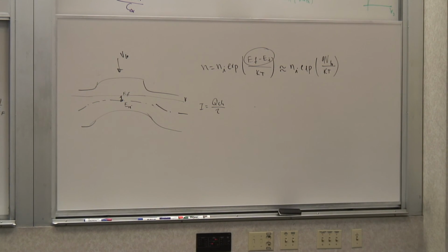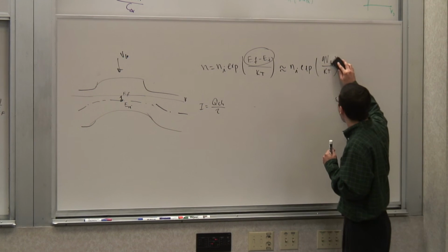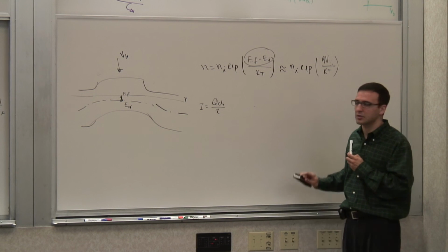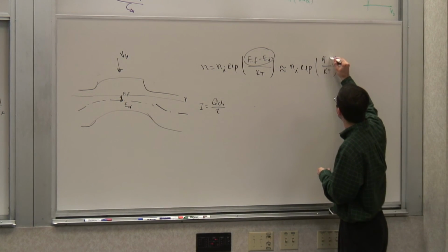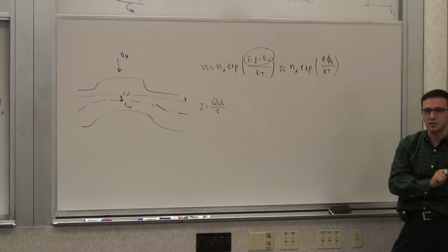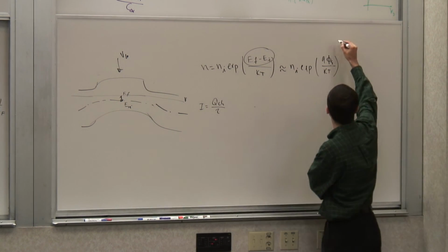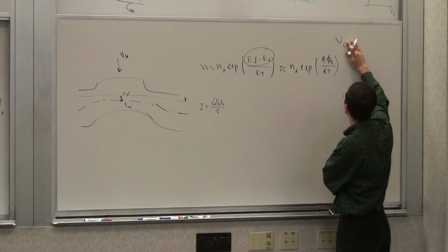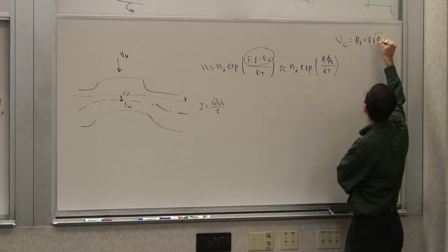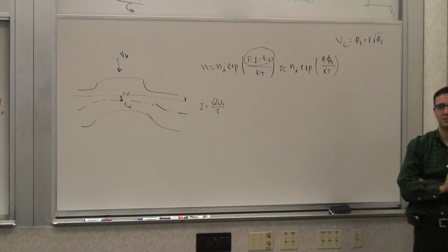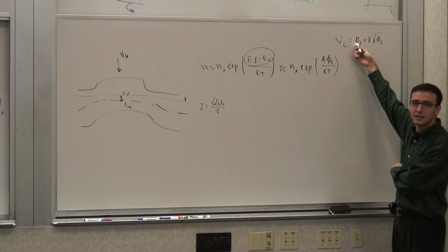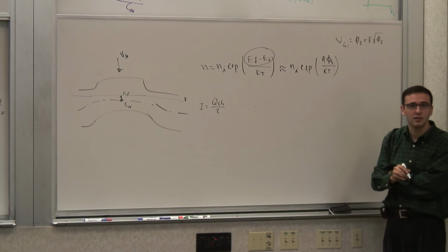Now, is it really a QVG? What it really is actually the surface potential, right? It's the surface potential that controls it. So this basically is the surface potential. Remember Vs? That controls how much this changes. But now Vs is related to Vg through a nonlinear expression. So Vg at that point was Vs plus gamma square root of Vs. Remember that? There are two terms to it. This was the potential drop across the depletion region, this was across the oxide.